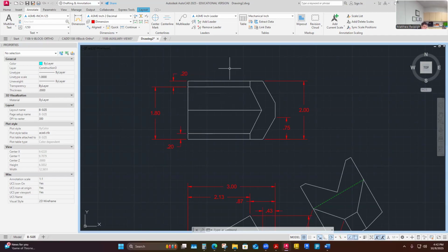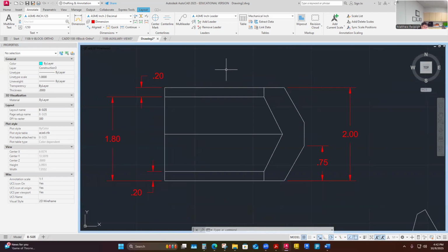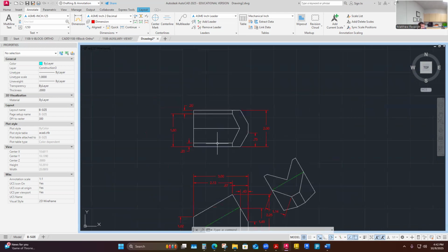And so we start to really get in the weeds on these dimensions, and that's just kind of what you have to do to analyze your part. It also takes a relationship with the part beyond what we have to determine: where are the critical holds, where are the dimensions pulling from and to, and then start to analyze these as reference dimensions or critical hold dimensions. Because the other one I need here is, if I look at the V surfaces here, how am I going to size those and locate them?